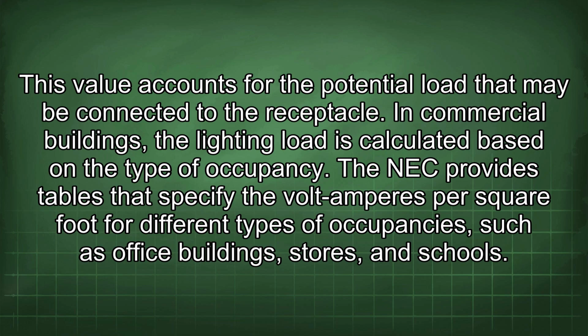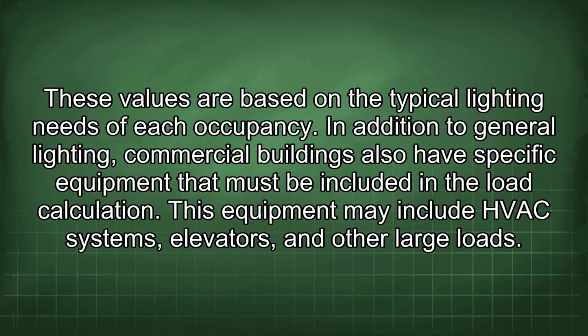In commercial buildings, the lighting load is calculated based on the type of occupancy. The NEC provides tables that specify the volt-amperes per square foot for different types of occupancies, such as office buildings, stores, and schools. These values are based on the typical lighting needs of each occupancy.